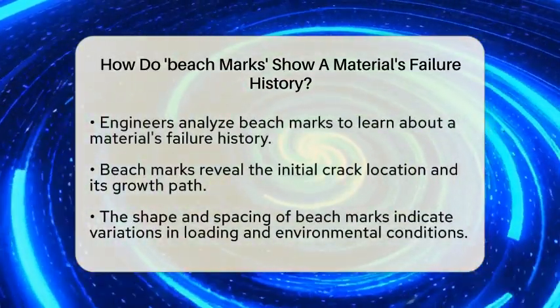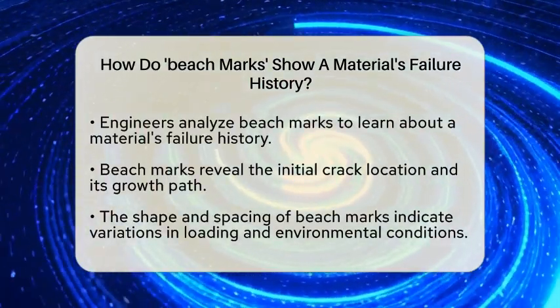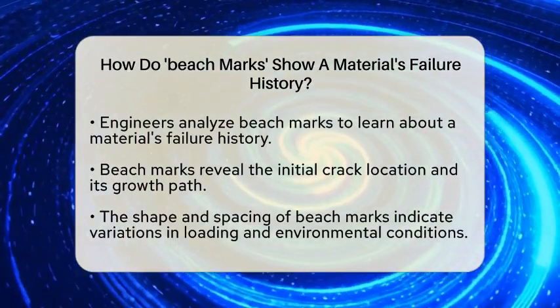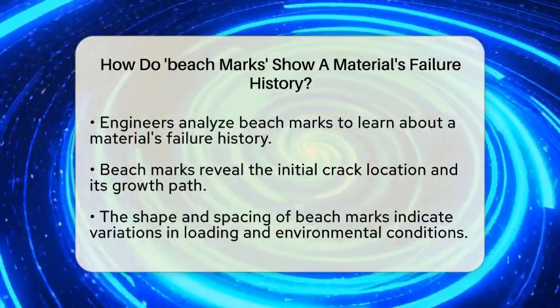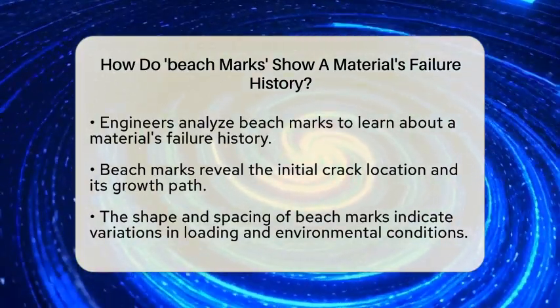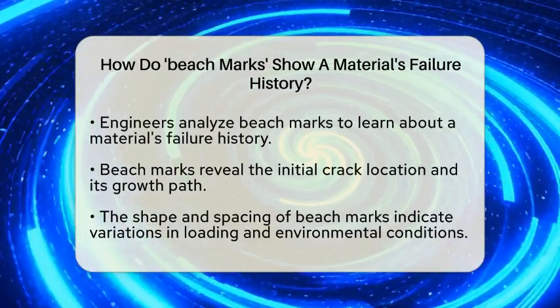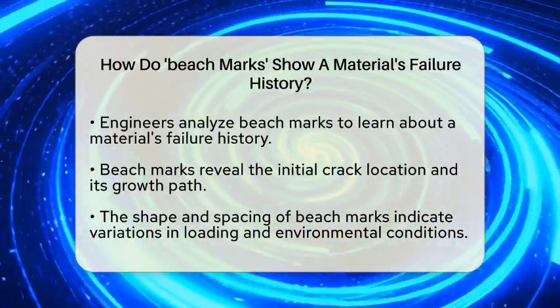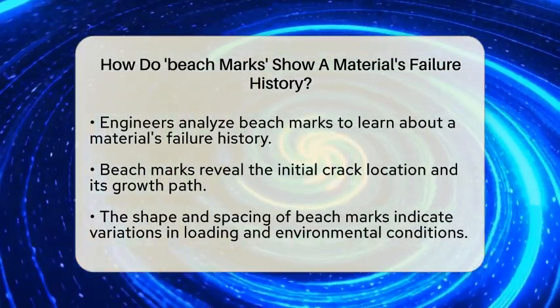When engineers examine beach marks, they can learn a lot about the failure history of a material. For instance, these marks can show where the crack began and the path it took as it grew. The spacing and shape of the marks can tell us about the variations in loading or environmental conditions that the material faced during its service life.